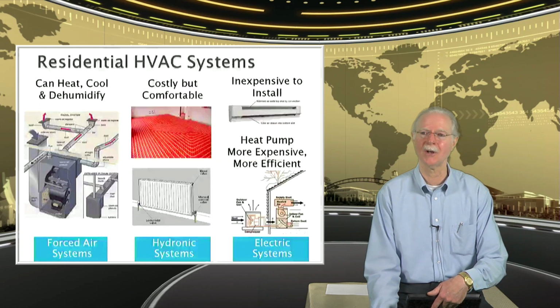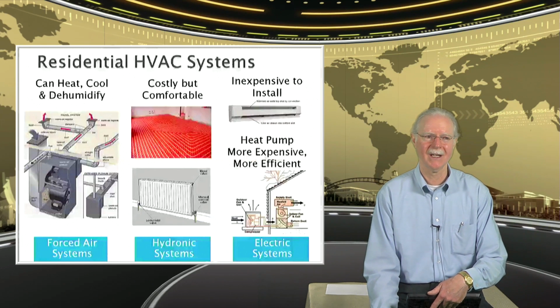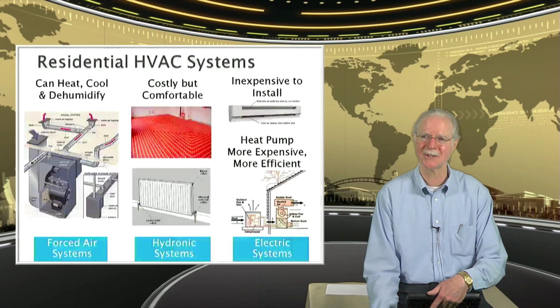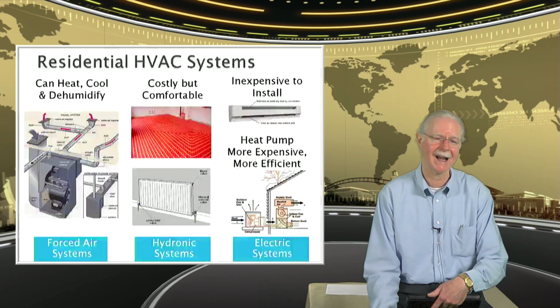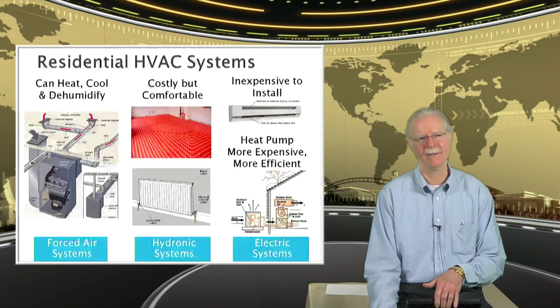You turn on a forced air system and you feel heat coming out of the ductwork right away. On the other hand, with hydronic systems, it's not a minute or two, it's tens of minutes and maybe even an hour before you even recognize a difference in the interior space. So you can actually have the occupants get in the way of efficiencies.